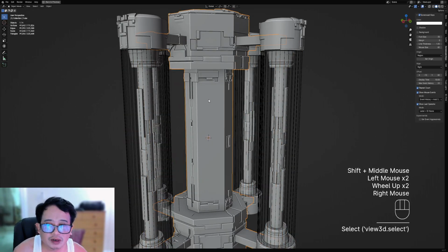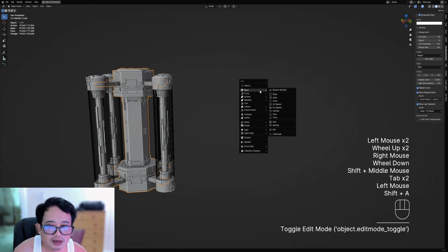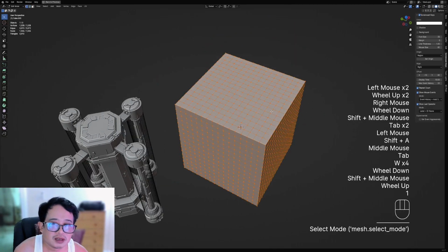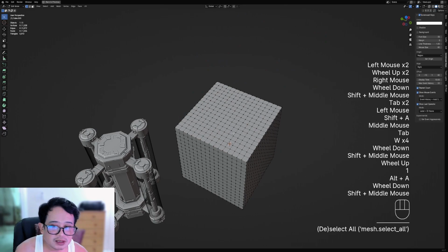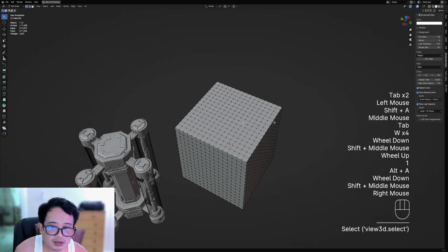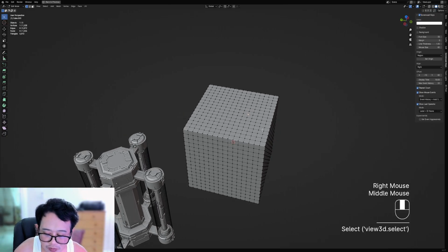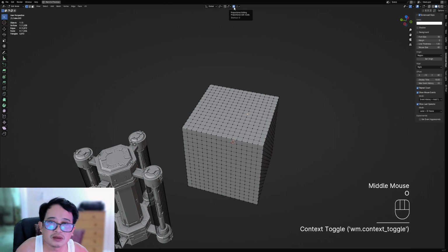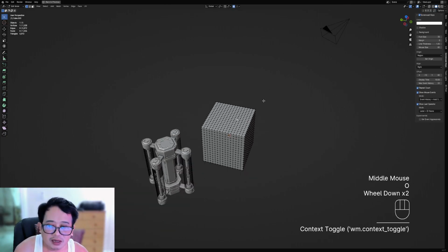And this is great for, okay, some vanilla Blender tutorial. So for example, this is a character and you're still using sculpt to grab a surface and pull and push on it. You can press O in edit mode to activate proportional editing and then grab.